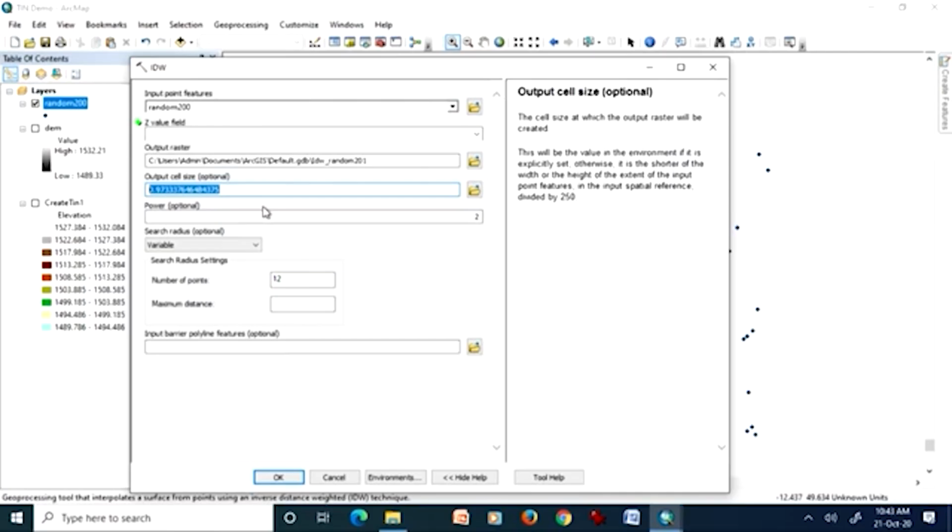If that is not there, then there is no use of increasing spatial resolution here. So, one has to be very careful. Generally, the default values come from already displayed themes or data sets, because it assumes that you are going to use these data sets along with the newly created digital elevation model. So it brings an already filled value, but definitely you can change that value.